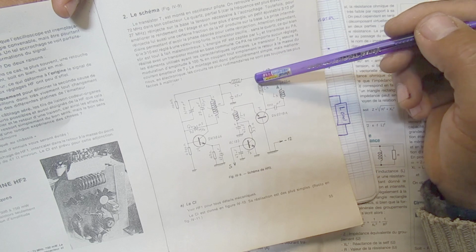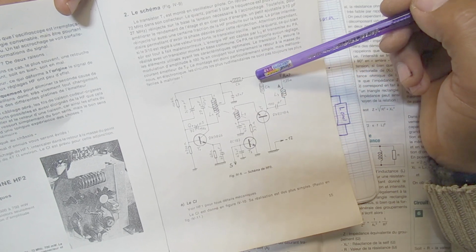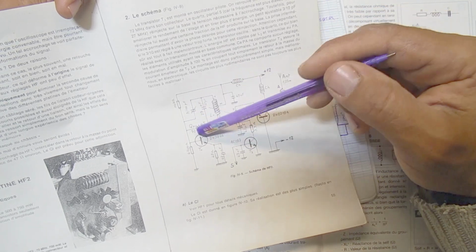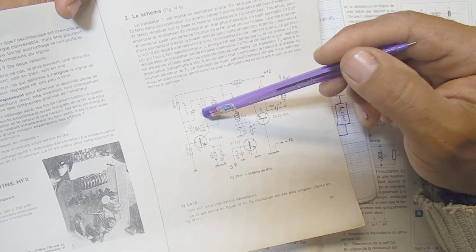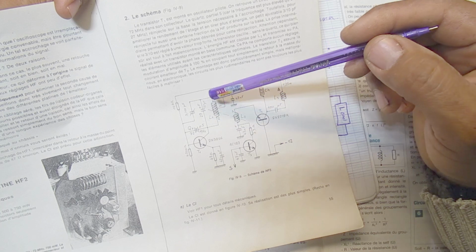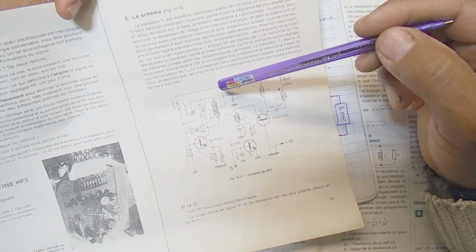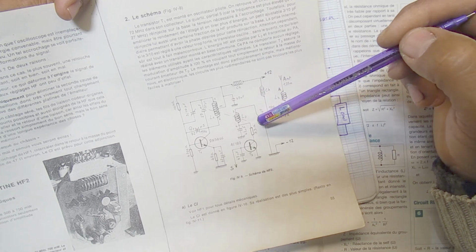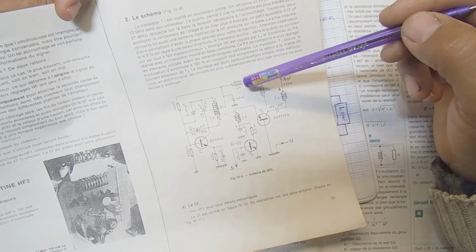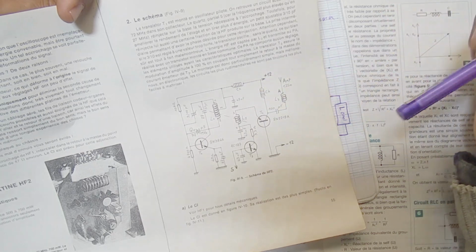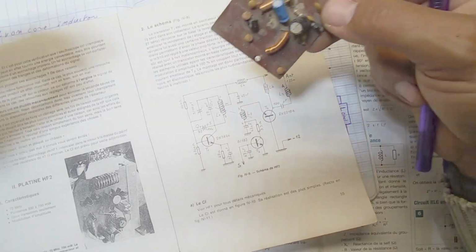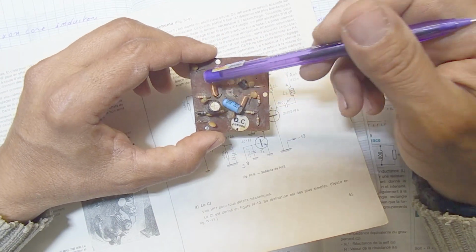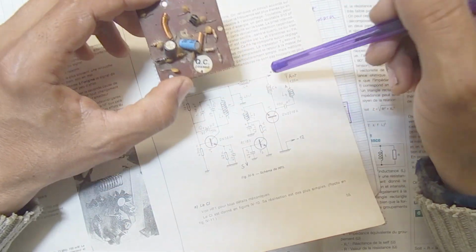Here we have the power voltage coming from the power supply, and in this part we have a high frequency oscillation, so we block this high frequency wave from getting out to the power supply from this part and from this part. So we have to use a choke here, like in this high frequency amplifier. They use it to choke here to block the high frequency from getting out to the power supply.